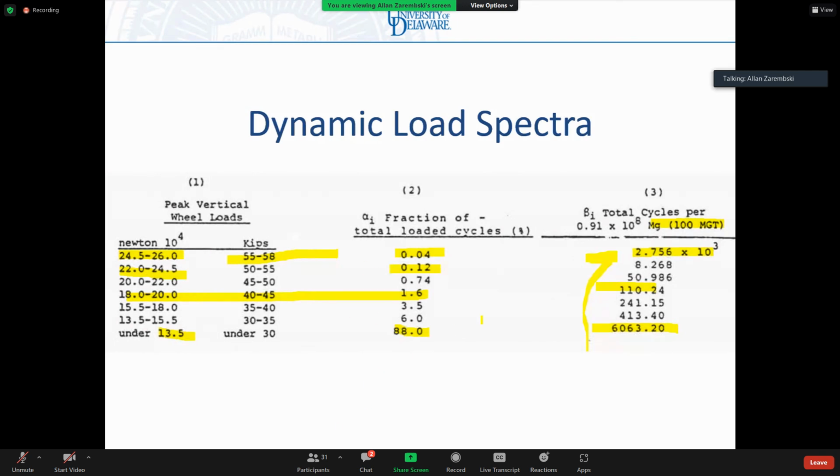So for example, if this equivalent stress is below the endurance limit, then the number of cycles to failure for all practical purposes is 10 million or infinite. So even though I have 6 million cycles, it's not enough to cause any sort of failure. Whereas at 25 kilonewtons, I may run this calculation and find that I only have 1,000 cycles to failure, in which case this produces a significant amount of fatigue damage.